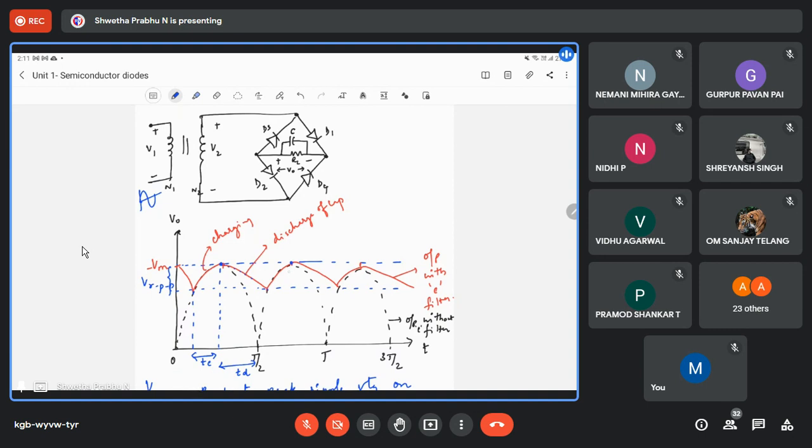As the secondary voltage, compare this waveform, that is the transformer output without filter, that is the rectifier output, along with the capacitor filter output. As soon as it falls below Vm, the capacitor starts discharging. And the cycle repeats for the next cycle.